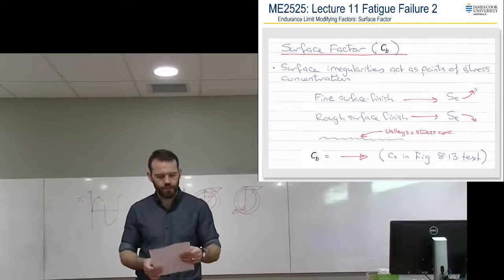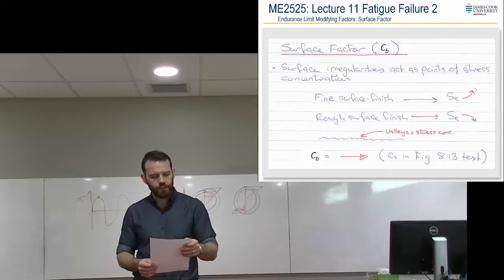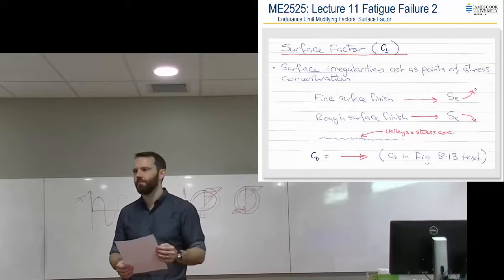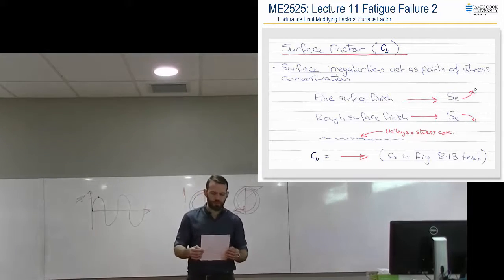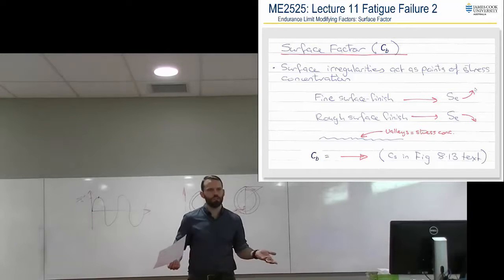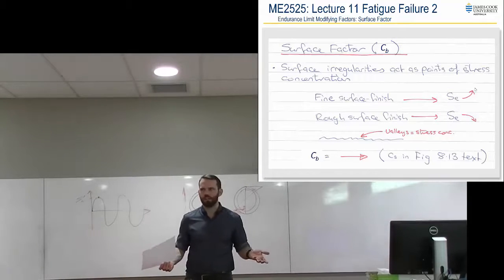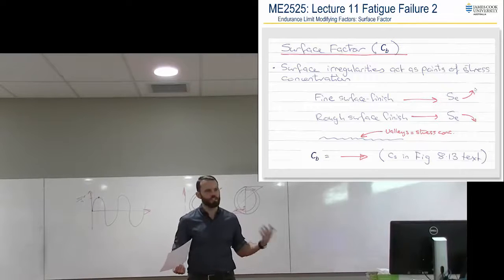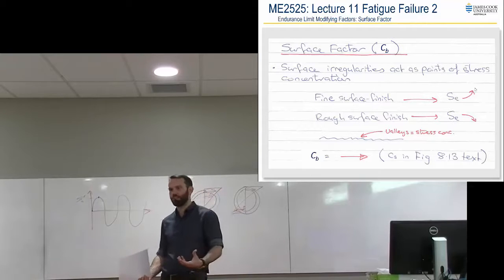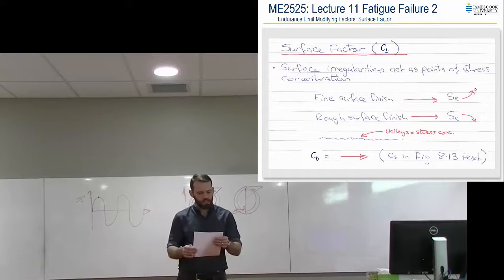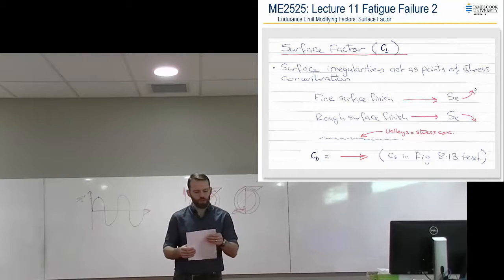Alright, pretty straightforward. Look at the very top line, which is technically the very top line of the grid, and you've got an arrow going to it, mirror polished, and for any tensile strength the factor is 1, which makes perfect sense to us because our experimental specimen is mirror polished. And so if we have the same surface finish as our test specimen, we shouldn't have any modification to the factor at all. Next line down is fine ground or commercially polished.